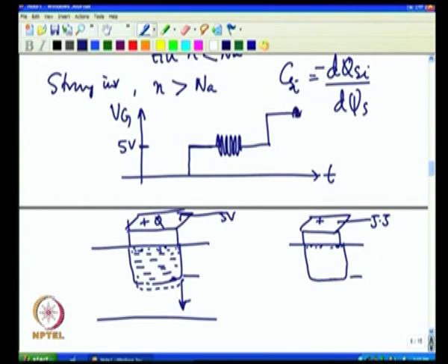So, what happens? This small signal I can't generate electrons. So, the edge of the depletion region moves back and forth, because the WD max has reached here and WD max has reached here in inversion, the capacitance does not change, and also the capacitance does not go to Cox because electrons are not responding.